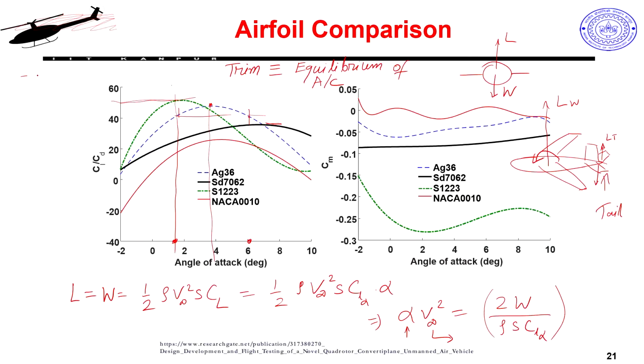So, you can think of a stick like this and I have some force, which is my lift force, acting here, and at the same time there is a moment which is bringing it nose down. So, what do I do? If this is my CG, I have to of course apply some force. Well, CG would be probably closer to here, not quite here. So, I must apply some force which would actually balance this lift also and overall.